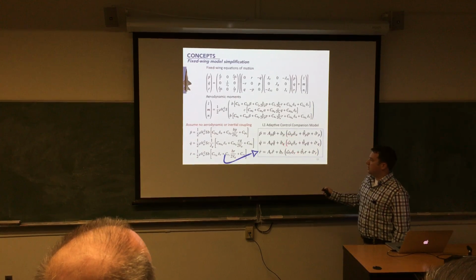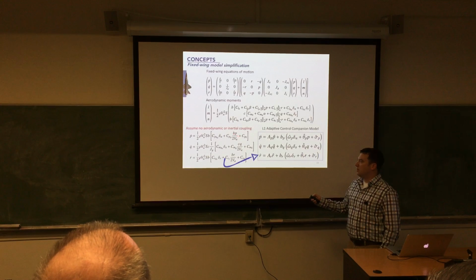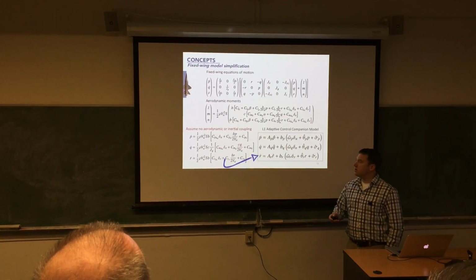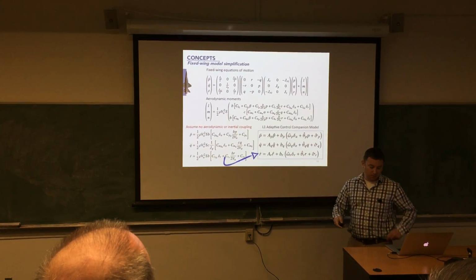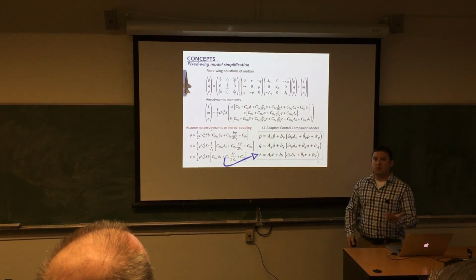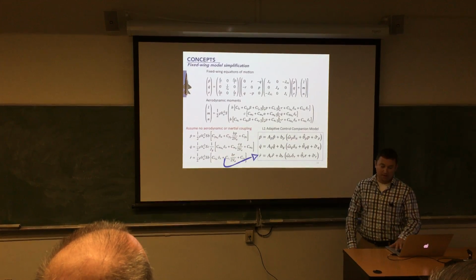In order to produce this, I make a very big assumption that there's no aerodynamic or inertial coupling. That's a pretty bold statement. It's obviously grossly incorrect, but as it turns out, the fast adaptation and robustness proved a very stable system, and it essentially acts as noise that is accounted for by the controller, and you can totally disregard it, which is an amazing find.